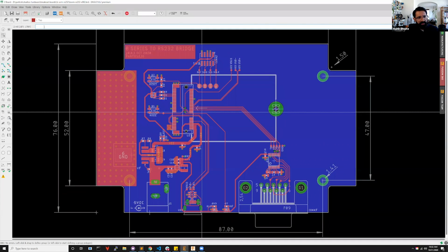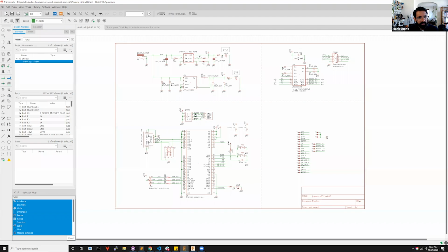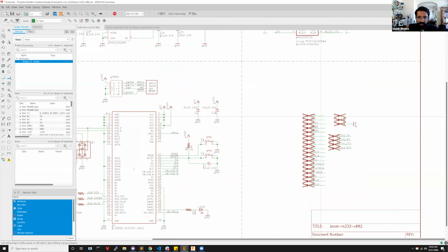There's one other tip that I wanted to talk about in Eagle, which is variants. I don't know if you guys are aware. Variants allow you to use the same schematic, but decide which particular subsections will be populated or not. For example, these test points will show up as parts on your bill of material, and you don't want that. So maybe I can create a variant called prototype, where these will be marked out. So when I generate a bill of material, these won't show up.